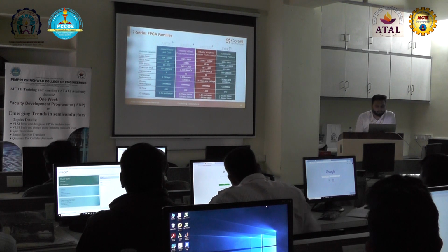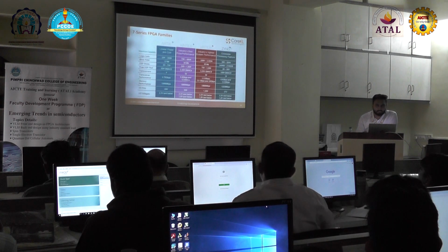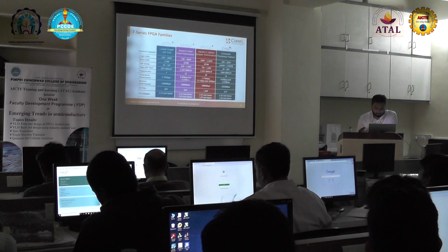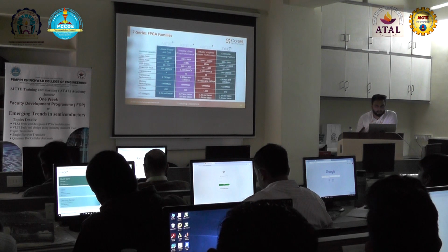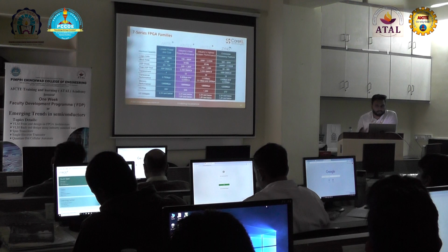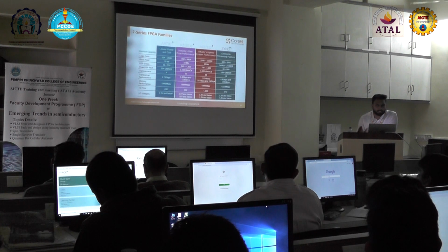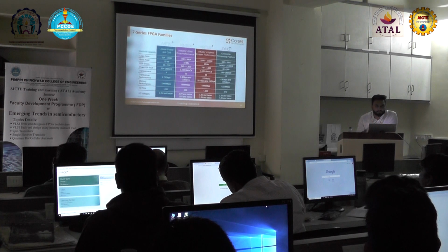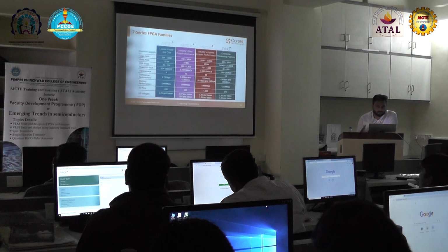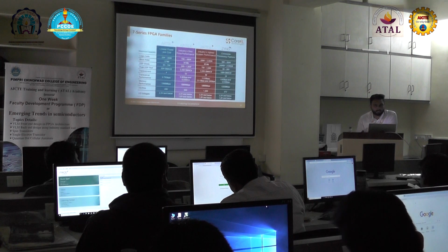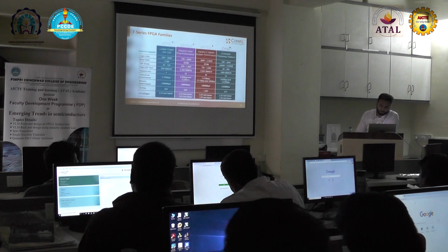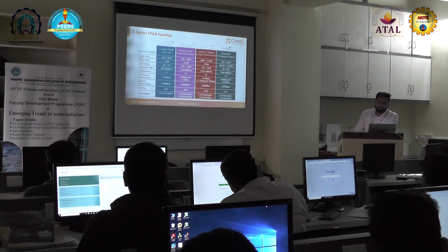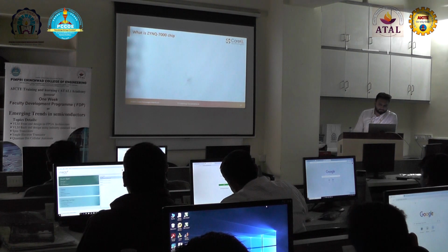So now we understand what the different series are: 7 series, and after Zynq 7 series, we have Zynq UltraScale, after that UltraScale Plus, and then Versal with 6 nanometer, right? From 28 nanometer to 20, 20 nanometer to 16, 16 nanometer to 6 nanometer. This is all about the 7 series FPGA families.